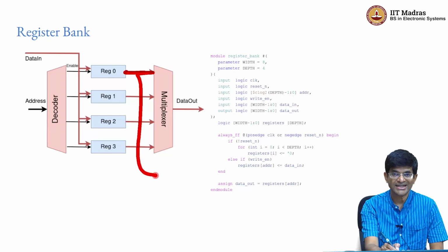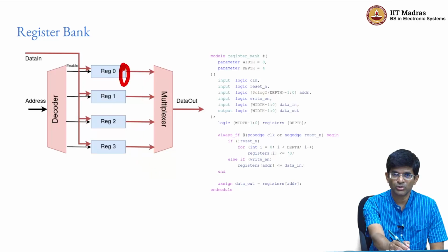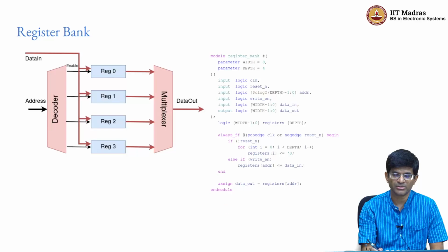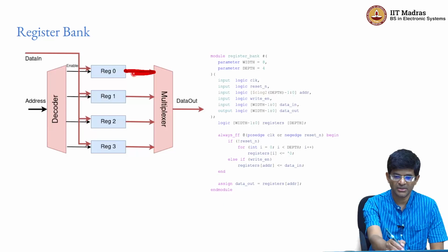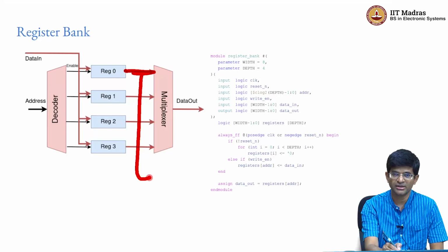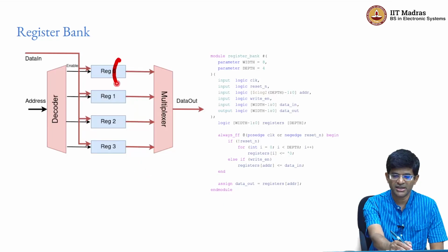It does increase the load on this output of the register, and as we have hinted at various points, what that affects is the final propagation delay through the gate, right. So when there are multiple things that are connected to the same point, what ends up happening is that the propagation delay, the TCQ or output delay of this register, is going to increase.